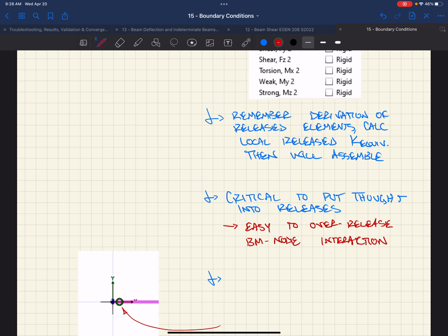Does RAM do that when you check it? Yeah, it does the direct analysis method, which takes into account, one, you have to reduce stiffness of your members, and direct analysis does that. Then it's taking on those notional loads, which takes into account the fact that you have an inherent misalignment.